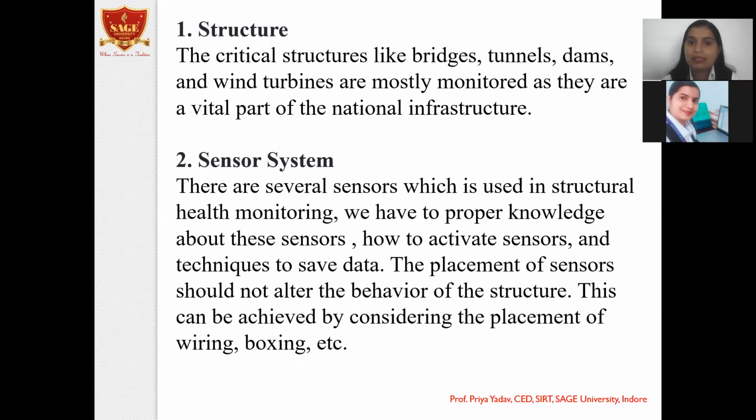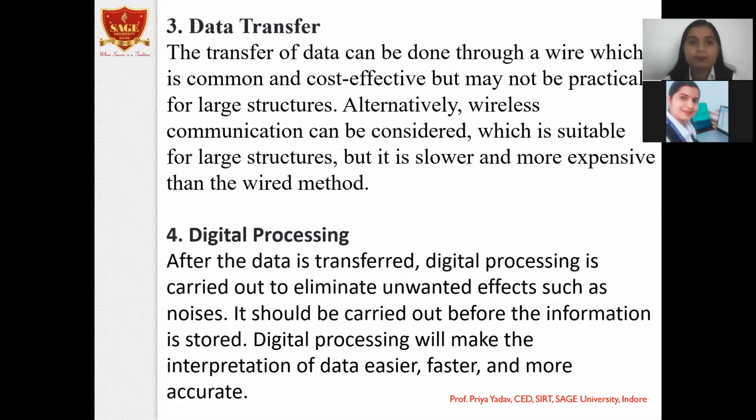There are several sensors which are used in structural health monitoring. We must have proper knowledge about the sensors, how to activate the sensors, and techniques to save the data. The placement of sensors should not alter the behavior of the structure. This can be achieved by considering the placement of wiring, boxing, and so on.